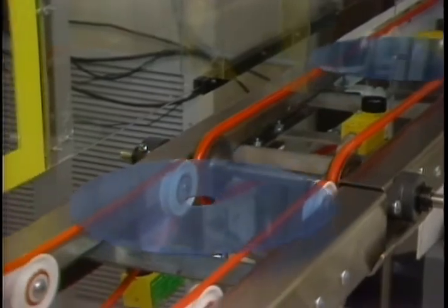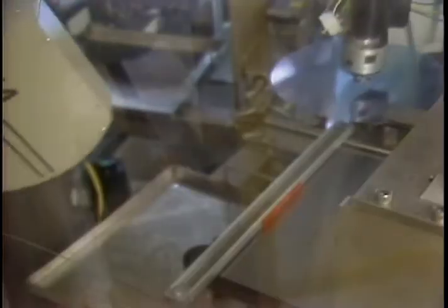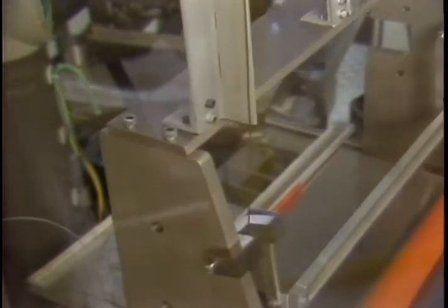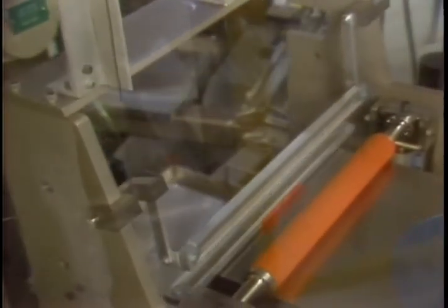A conveyor delivers polymethyl methacrylate plastic substrate coated with an ultraviolet sensitive photopolymer to the replicator. Robots transfer each from the conveyor to the replicator. The substrate is embossed by the stamper. An ultraviolet light cures the polymer within about 10 seconds. The robot moves the replicated substrate to another conveyor.